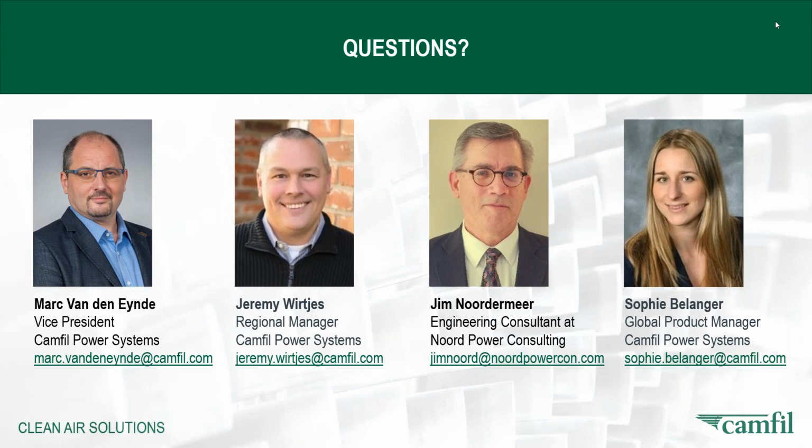Yeah, I think that's exactly why it's so important to understand your operational mode as well as your environment in detail. It does not mean that everywhere in the world you should put E12 to protect your gas turbine. You could have sites where the environment is not as highly dust loaded, or very fine dust concentrations are not that high, and therefore an E11 would probably protect your engine as well as an E12 in a very high dust loaded environment.